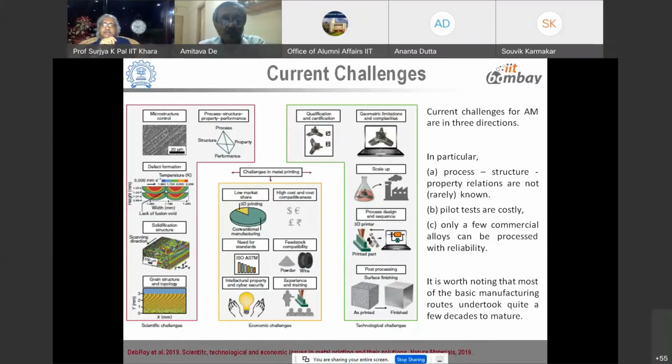Those who have been involved in some casting or welding processes, analysis work, we already know that if we melt material by a traveling source, there would be solidification, and there would be different directions of the growth of crystals depending on the direction of heat flow, heat loss, heat dissipation. Depending on that, there would be different kinds of cooling rates, and different cooling rates will lead to different kinds of segregation of alloys, structure that would impact the property, and that would impact the performance.